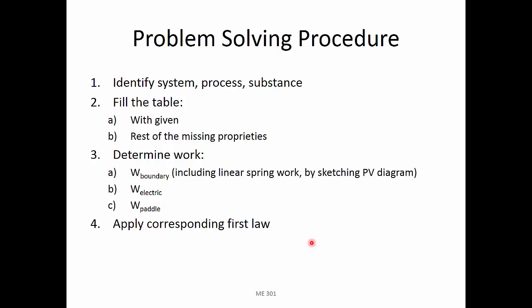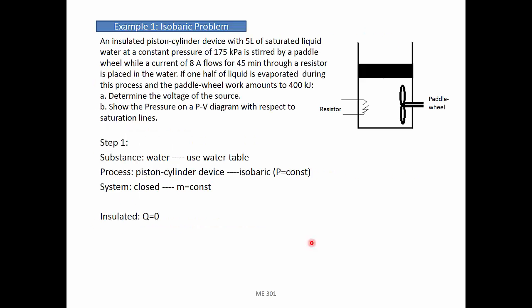Follow the same 4-step problem solving procedure. Identify system, process, and substance. Fill the tables. Determine work. And apply the corresponding first law.